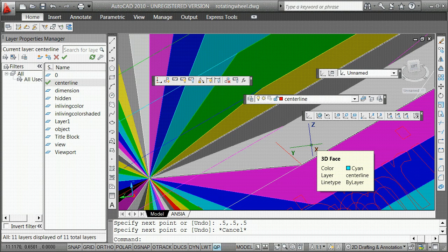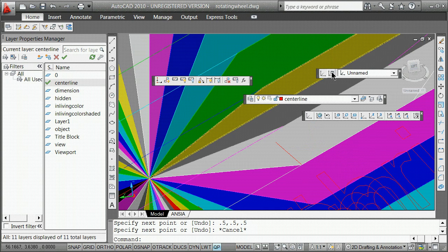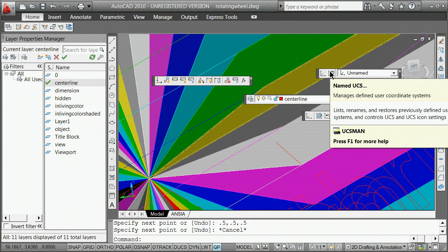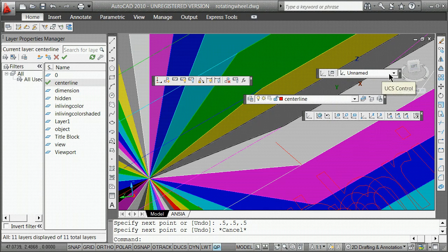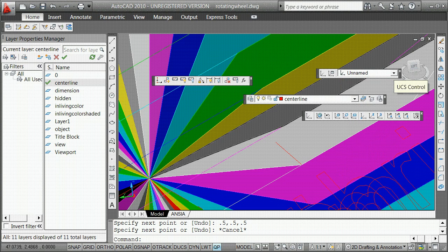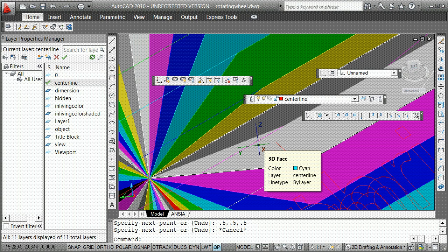When you make a coordinate system, it's a really good idea to save it if it's important. And there they are, a named coordinate system. I'm going to type this and we'll check later how you go about doing it. You see I've got a bunch of these already defined. Those are all my coordinate systems. Coordinate systems are not views, but you can align coordinate systems with views.